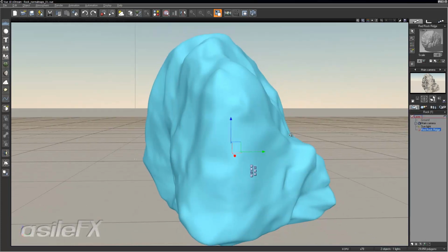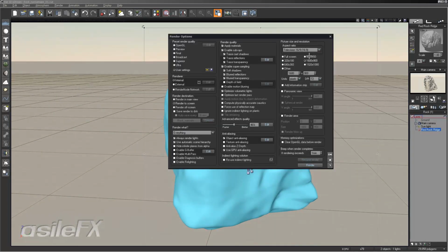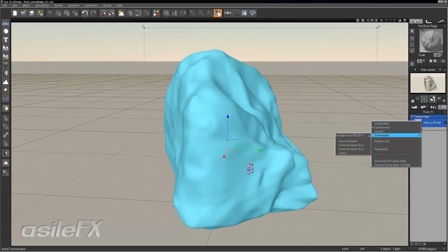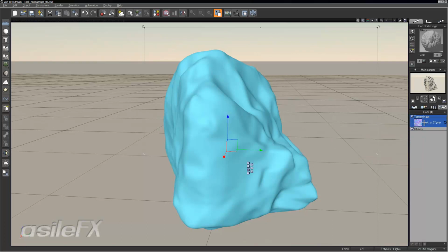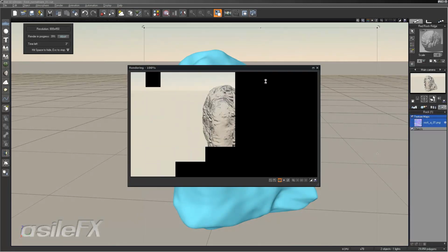Of course, that's with a material scale of 1. And we don't need to render this so large. Now what we can also do is, you can go into the texture map, in the links tab, right click, and we could downsample it to a lower resolution. We divide it by 8 right now. Go ahead and render. It still looks pretty good.